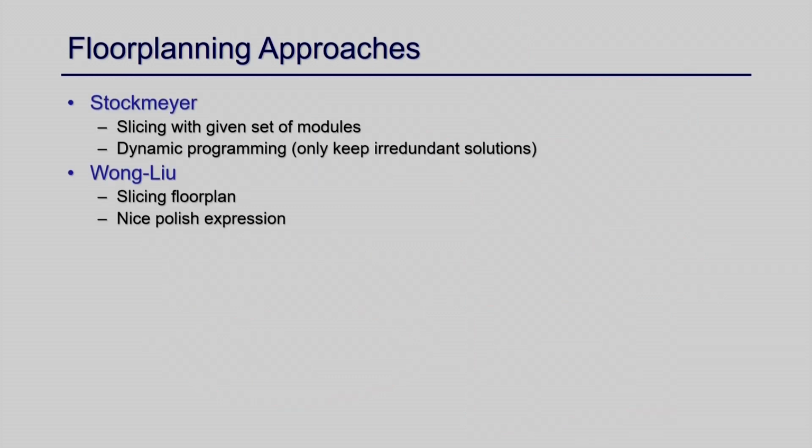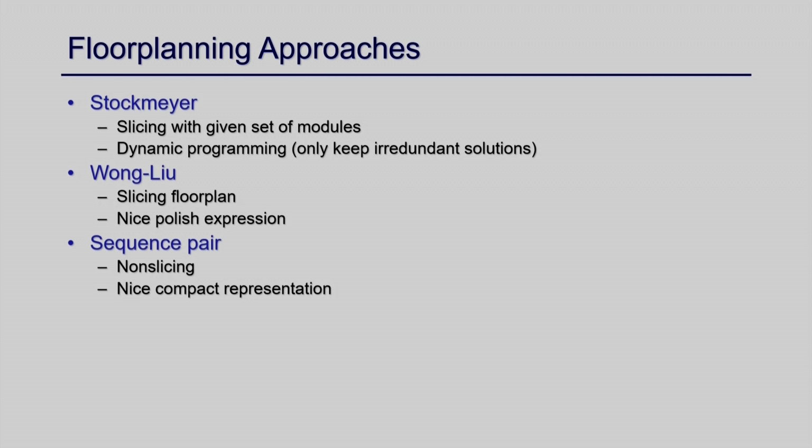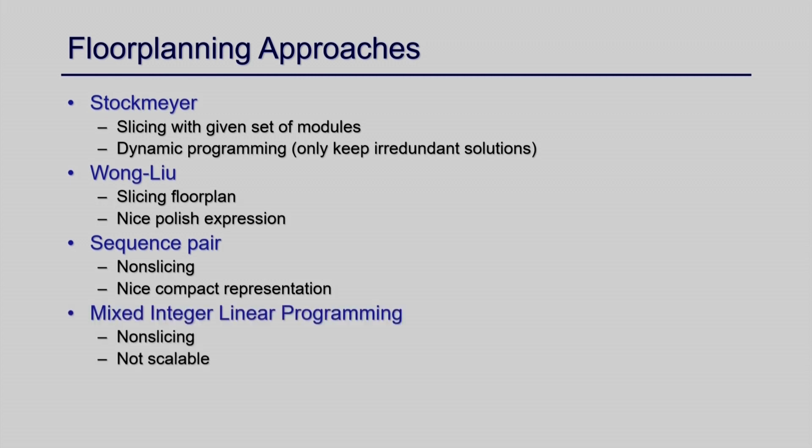Again, in floor planning there are a lot of approaches, and because this is an NP-complete problem, an optimal solution cannot be obtained by some optimal algorithm. So, various kinds of heuristic approaches are also available for this step as well. Okay. So, I move on to the next step, which is placement.